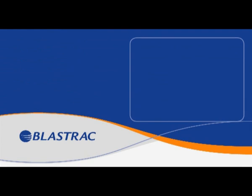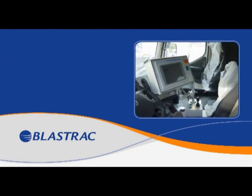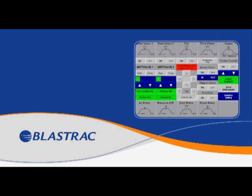Now switch on the PLC unit using the touchscreen panel inside the truck cabin. Engage the hydraulic system by switching to it using the touchscreen system and mechanical clutch of the truck gearbox.